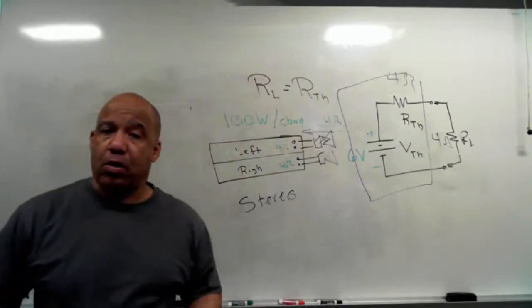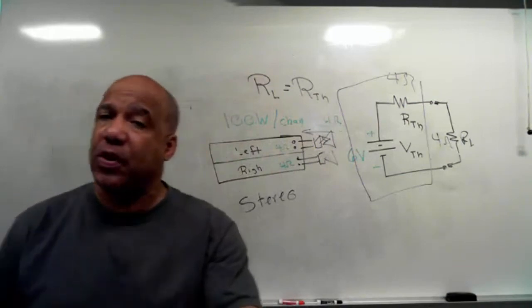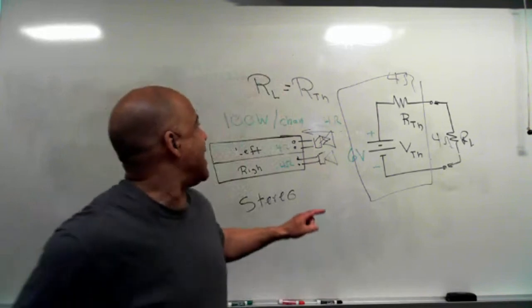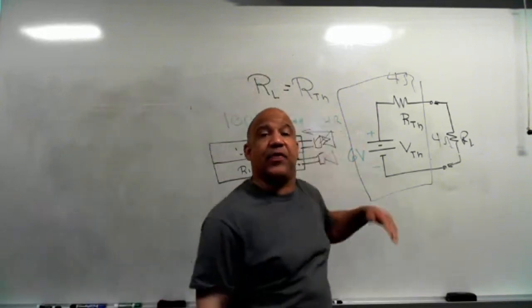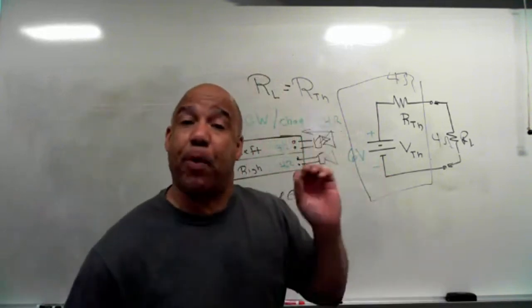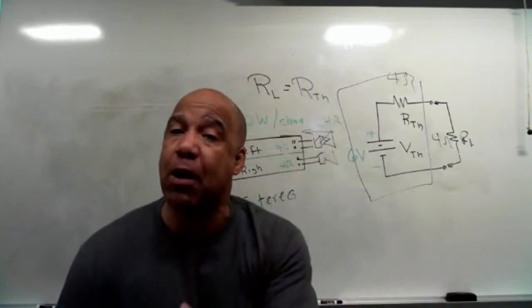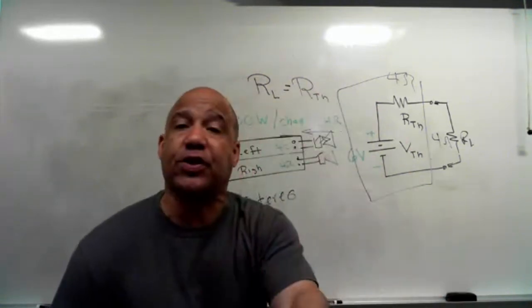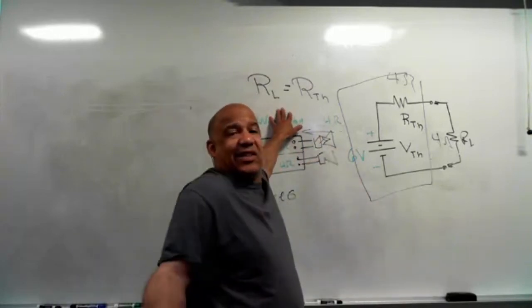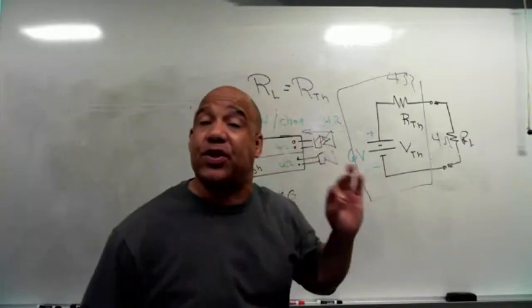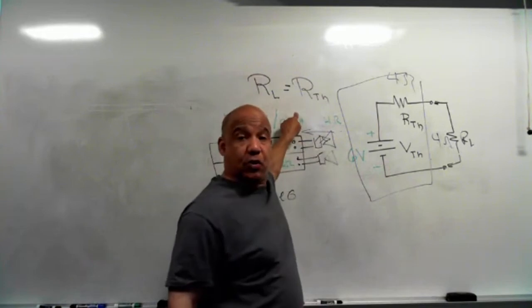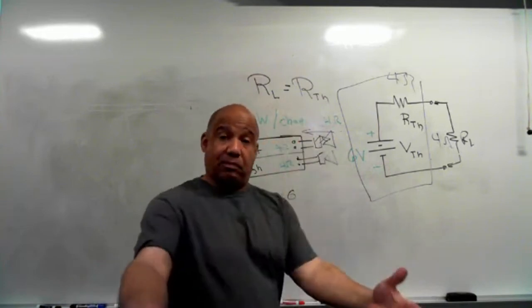Maximum power transfer theorem. Now don't confuse this. I'm not saying that these two have to match. They only have to match if the purpose of your circuit is to get maximum power from the power source to the load. If that's not your concern, don't worry about this. But if that's your concern, that only happens when this is true. And with an amplifier, that's what you want.